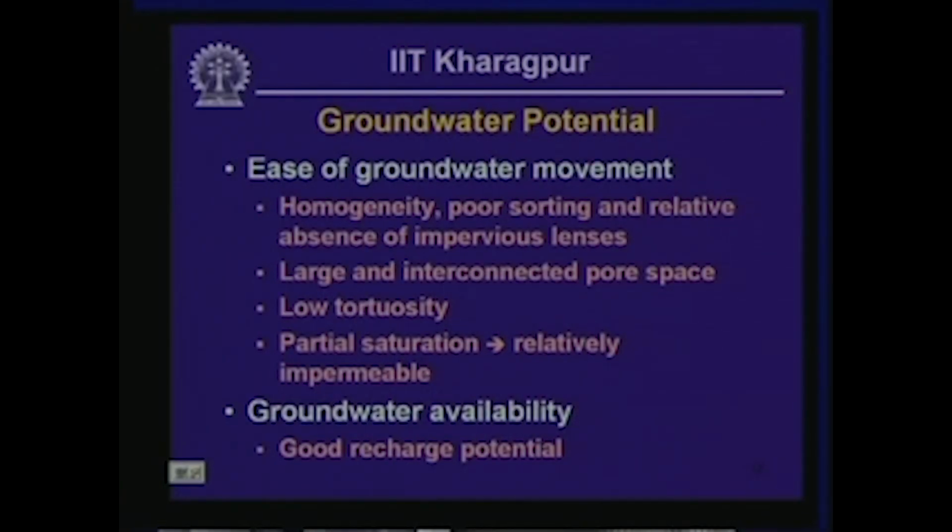Then the second point to consider while considering groundwater potential of a deposit is that the formation preferably should have large interconnected pore space. Low tortuosity, that means the interconnected pore space should be aligned without much deviation from a straight line.